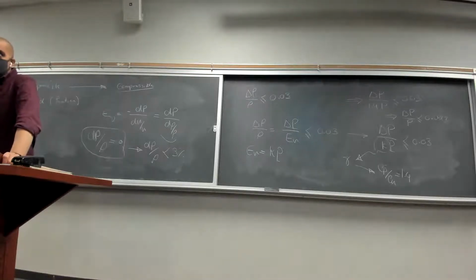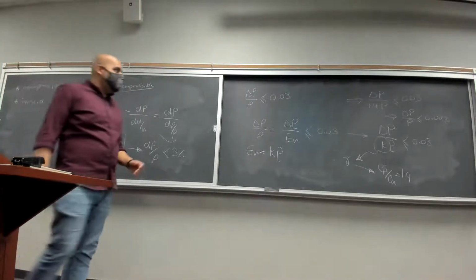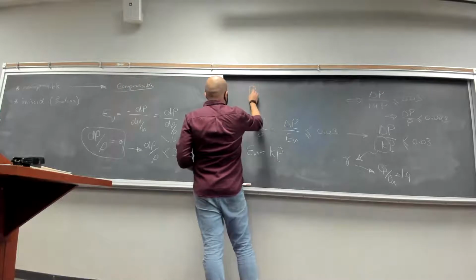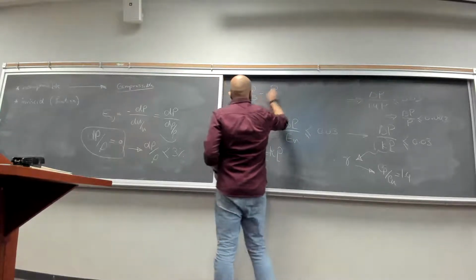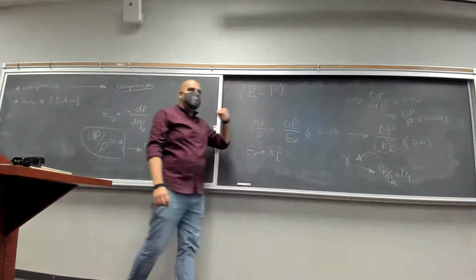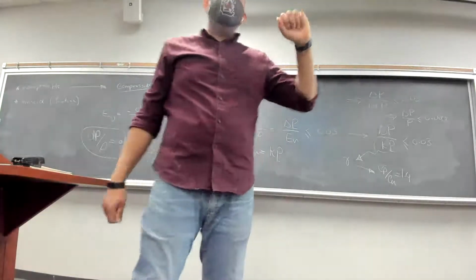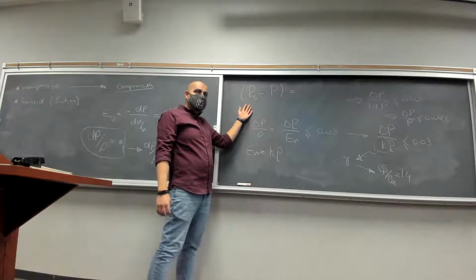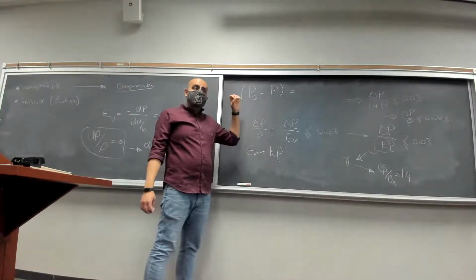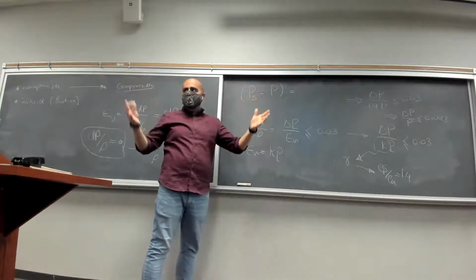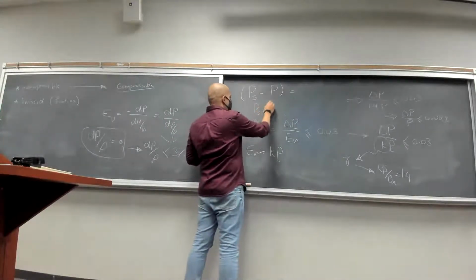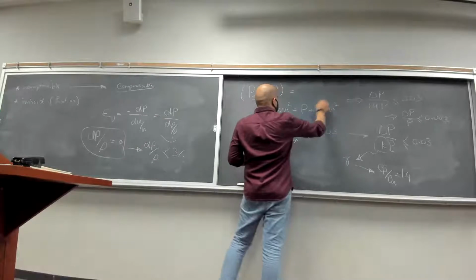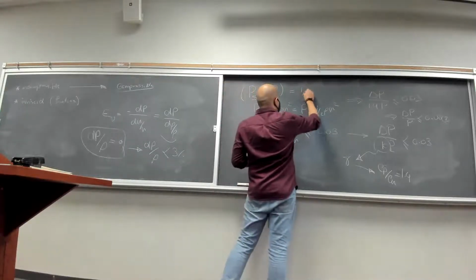How can we relate pressure differential to velocity? Let's say this pressure differential is between the stagnation pressure and the static pressure. All right? A stagnation and a static. How was this related to velocity? Does anybody remember? What was the main characteristic of the stagnation pressure? It is the point at which the velocity is 0, right? In general, stagnation points are points at which velocity is 0, right? So if you apply the Bernoulli's equation between this point and the static pressure at the same point, velocity is 0. So Ps minus P is going to be 1/2 rho v squared.